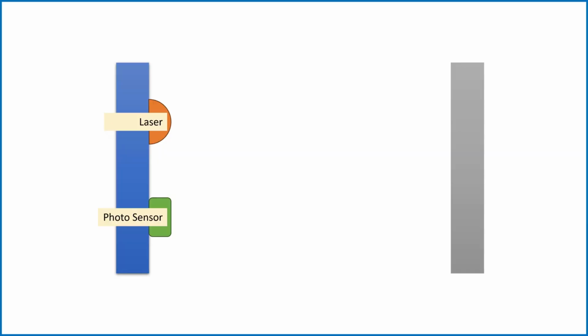So let's first go over the general idea of how a Lidar works. A Lidar, or a time-of-flight sensor, is used to find the distance between it and the nearest obstacle in front of it. Now, a Lidar is made up of a laser and a photosensitive sensor. So what it does is first, the laser will emit a beam of infrared light. This beam will travel from the Lidar to the nearest obstacle in front of it. It will reflect off that and go back towards the Lidar.